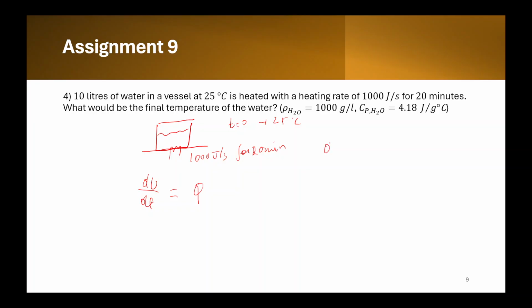So in this equation, in minus out, you can write m dot (h in minus h out). This term is basically zero because there is no flow of any fluid, plus q dot minus w s dot. This is also zero, only q remains. So this is how we get this equation.